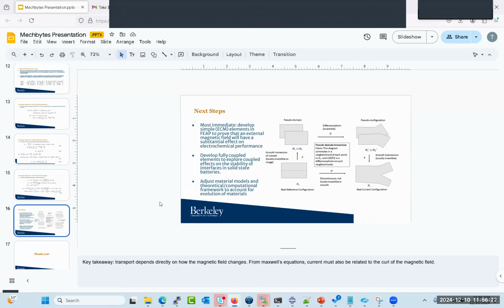Yeah, so they essentially solve all of these equations. If I neglect temperature, neglect deformation, and magnetism, of course, they essentially have exactly this system implemented. So what I'm going to do is apply boundary conditions for the magnetic field that are just zero Dirichlet. It should compare very close to their case, and then I'll have a non-trivial magnetic field boundary condition, and then hopefully I see some important or non-trivial differences. And that's sort of how I'm going to validate. They have theirs validated.